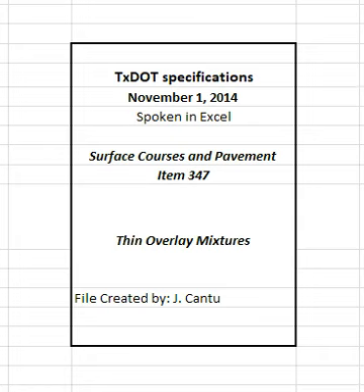Take additional water flow measurements when both of the following conditions occur. The temperature of the mixture before compaction is below 275 degrees Fahrenheit, and WMA is not used. The water flow rate should be greater than 120 seconds. Adjust the mix design or construction methods, when directed, if the water flow rate is less than 120 seconds. Allow the compacted pavement to cool to 160 degrees Fahrenheit or lower before opening to traffic unless otherwise directed. Sprinkle the finished mat with water or lime water, when directed, to expedite opening the roadway to traffic.